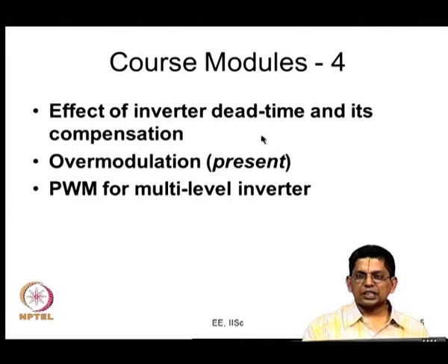Here we are considering the effect of dead time. The top and the bottom devices are not exactly complementary in an actual inverter, not switched complementarily. You switch off the outgoing device first and then you switch on the incoming device, which is the dead time, and we looked at what the effects of the dead time are. We analyzed its effect for continuous PWM methods. We found that for all continuous PWM methods the effect of dead time is quite similar and dependent on power factor. We also looked at the effect of dead time for bus clamping PWM methods.